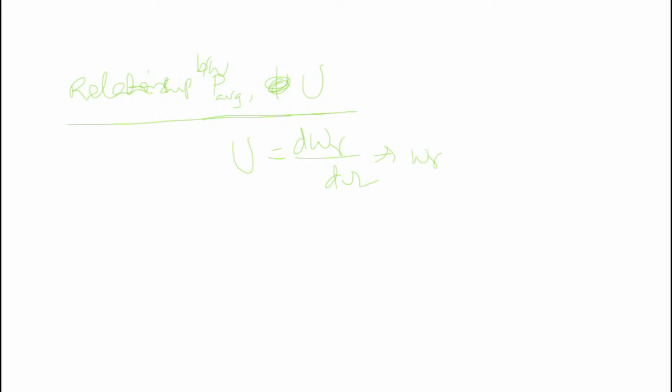From this, we have W R is equal to what? Integral U d omega. But radiated power, in the Poynting vector theorem, we discussed this one. Radiated power can be calculated by using the P average, that is integral P average dot ds. So you can see this one is equation 1 and equation 2. Both are same.